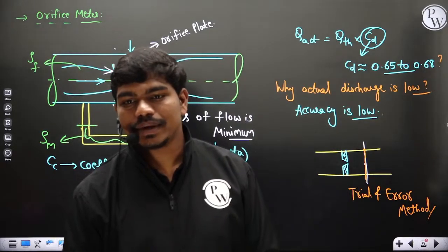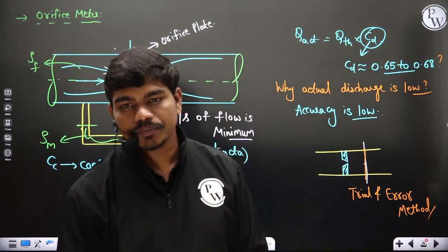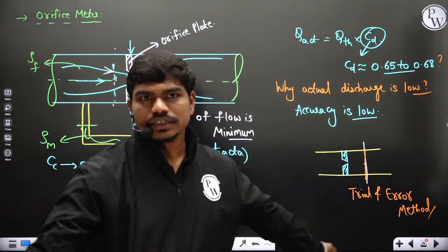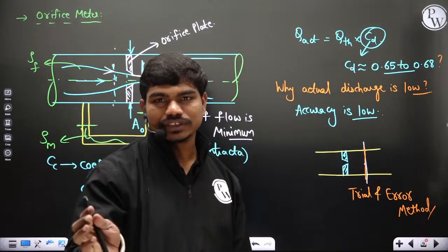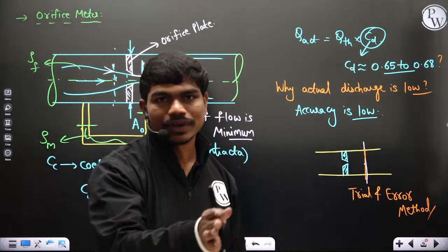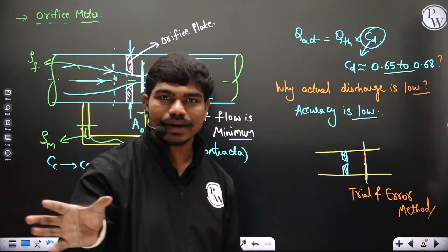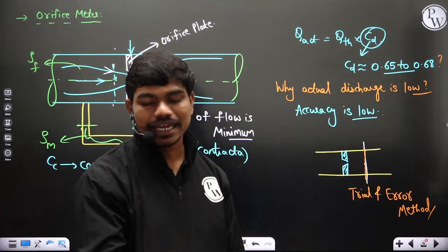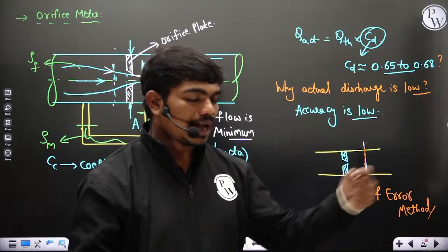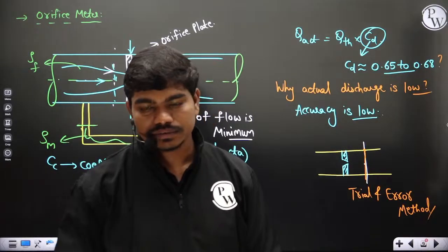Can we use this device at bends of pipes? Yes, generally we can use it at bends also, but we should give sufficient clearance to neglect the bend effect. It is not exactly at the bend that you connect, but somewhere just upstream of the bend and downstream of the bend.